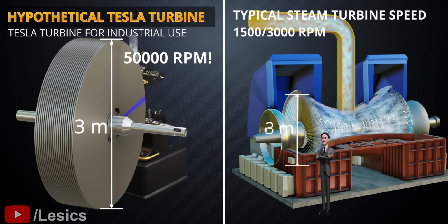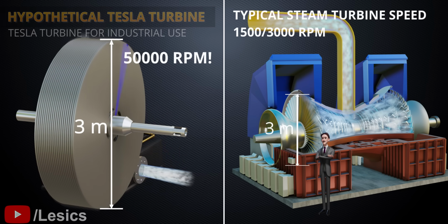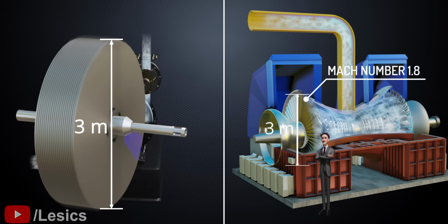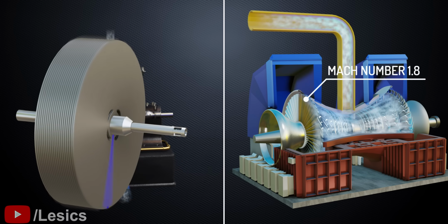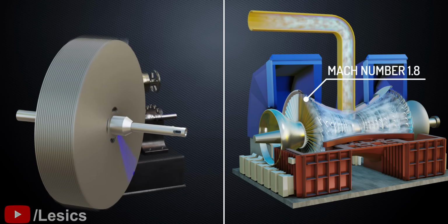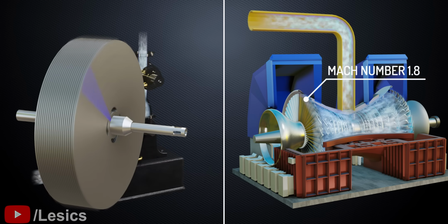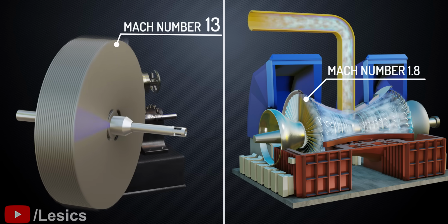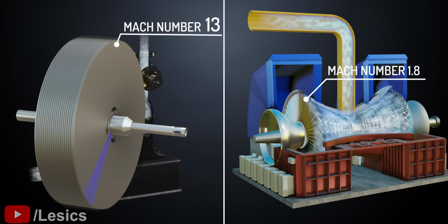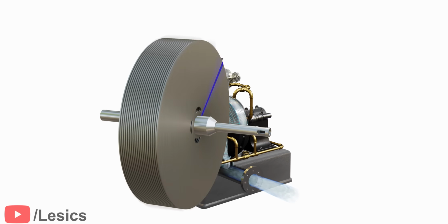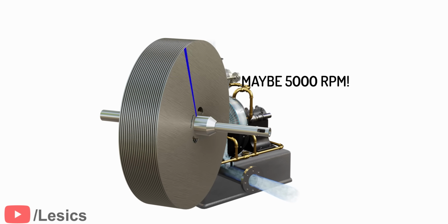The main issue is that of the blade tip velocity. The most modern steam turbine blades are able to achieve a Mach number of 1.8 at their tips, or 1.8 times the speed of sound. A rough calculation shows that these hypothetical disks will be having a Mach number of 13 at the tips. Definitely an engineering impossibility. The only option left is to reduce the RPM, and we know this act will lead to a huge drop in the turbine's efficiency.